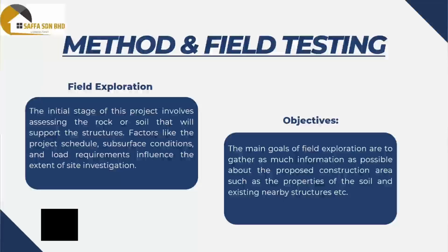Method and field testing. Field exploration. The initial stage of this project involved assessing the rock or soil that will support the structures. Factors like the project schedule, subsurface conditions, and load requirements influence the extent of site investigation. The main goal of field exploration is to gather as much information as possible about the proposed construction area, such as the properties of the soil and existing nearby structures.